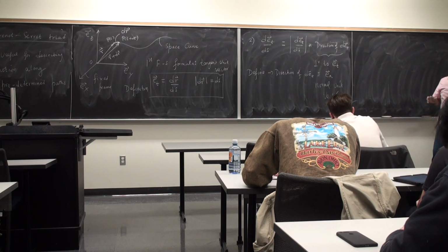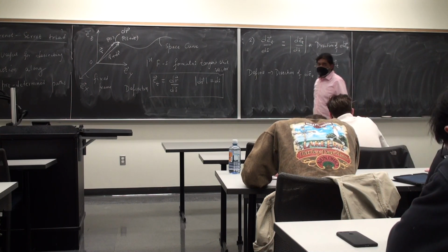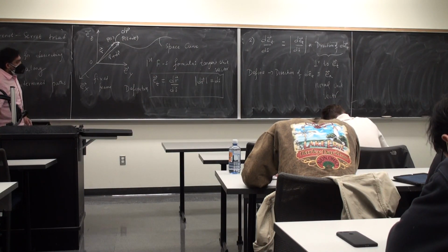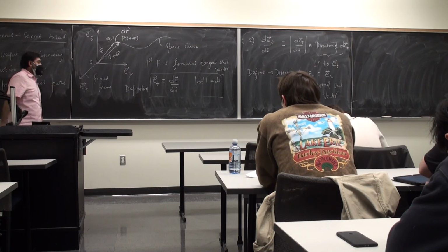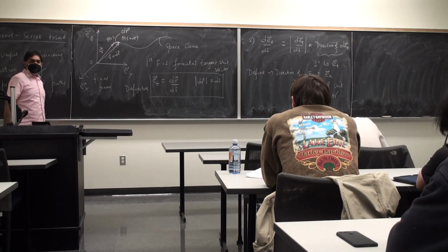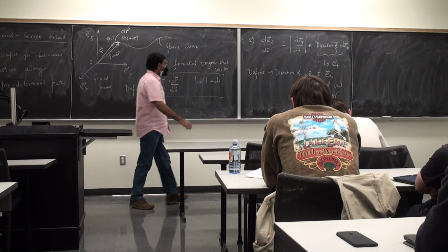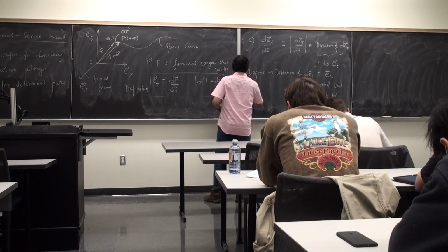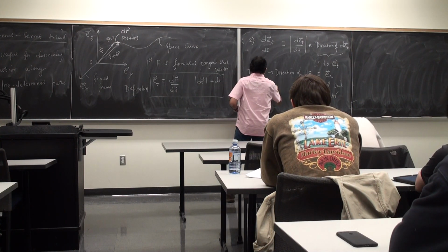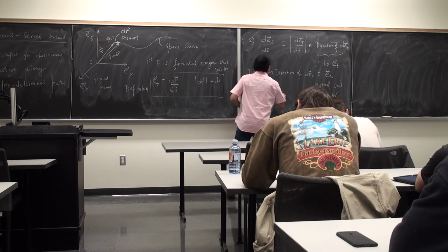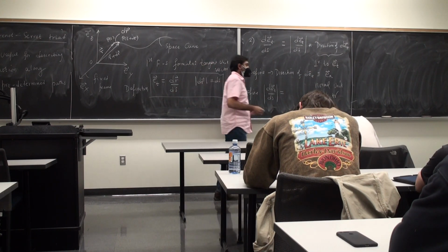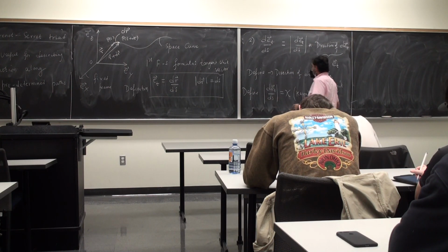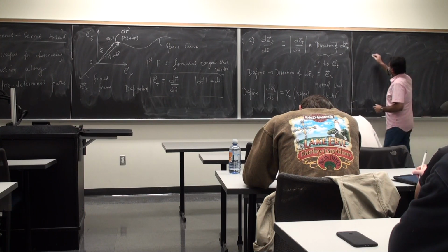And what we are doing essentially is going into differential geometry or surface geometry. This is all elements of surface geometry and screw theory and all these things. We will not go into the details of some of those things. We will stop at whatever is useful to us. One can dig very deep into this and take a whole course on this. I'm going to define that magnitude term, det by ds, to be a term called kappa, the Greek letter kappa, where kappa is called the curvature of the space curve.